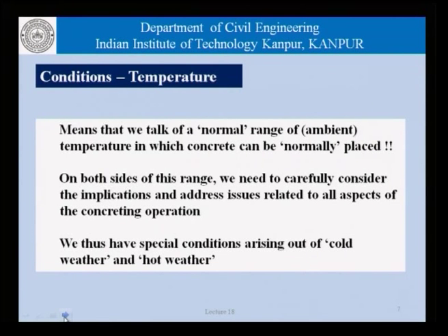As far as conditions are concerned, let us talk about temperature, which is the subject of concern for our discussion today. What we mean to say is that we talk of a normal range of ambient temperature in which concrete can be normally placed. That is, we do not have to take any special precautions for the concreting operation so long as the ambient temperature is within a normal range. On both sides of this range, therefore, we need to carefully consider the implications and address issues related to all aspects of the concreting operation.